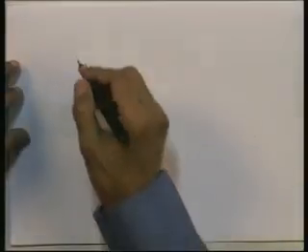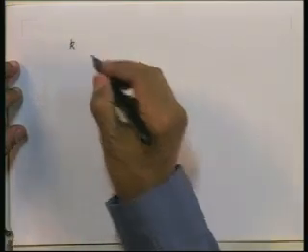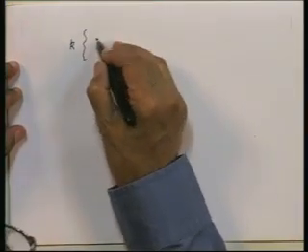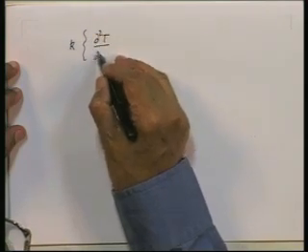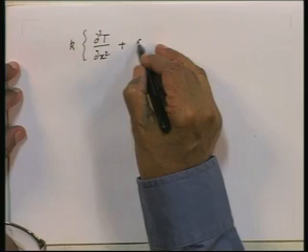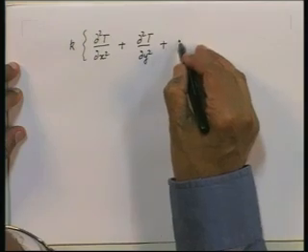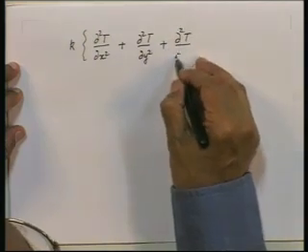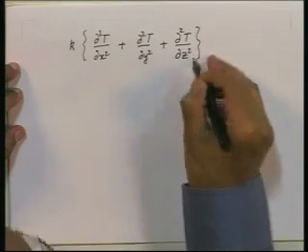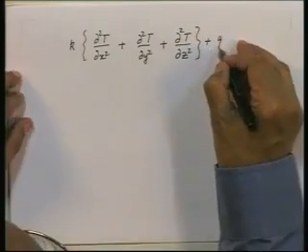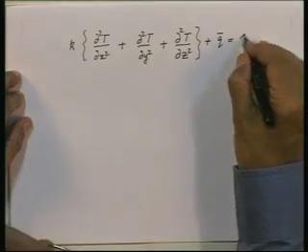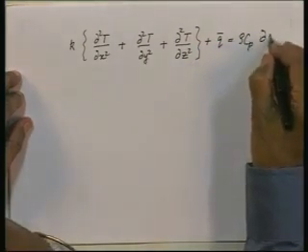In order to put down the differential equation, let us look at our general differential equation. If k is a constant, it is k multiplied by d2T/dx squared plus d2T/dy squared plus d2T/dz squared, plus q bar, is equal to rho Cp dT/dt.